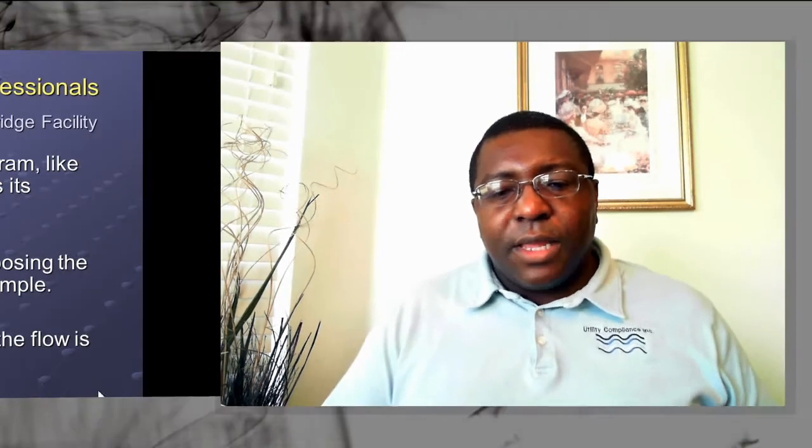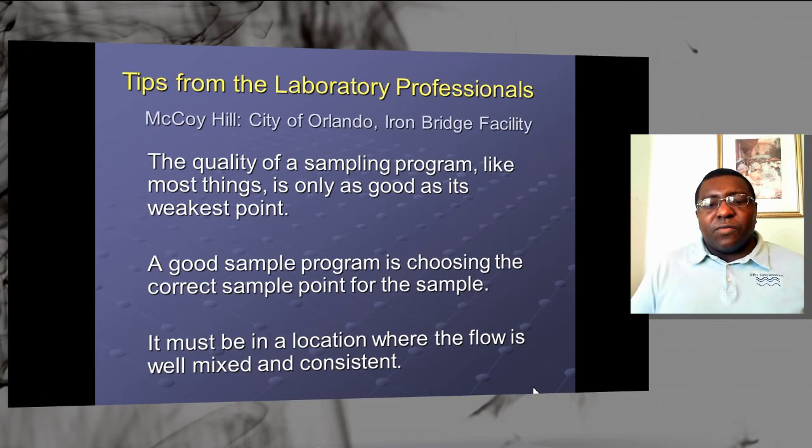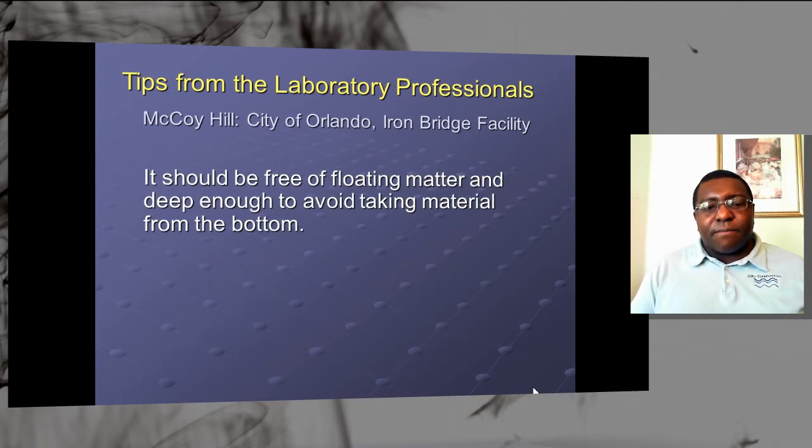If you want it a foot down from the water, or half of the tank dimensions, however you word it, put that in the sampling program. And the location where the flow is well mixed and consistent. Don't go to that dead spot in the tank just because it's easier to reach. You may have to adapt some sort of extension on your pole or build some sort of way to reach the most representative sample in that tank.